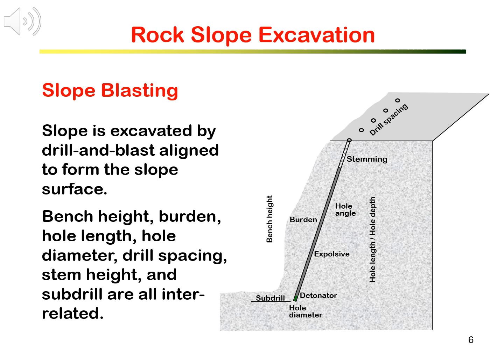A series of holes are drilled in such orientation and alignment to become the slope surface. Key geometrical parameters of drill holes and explosive charges are illustrated here. After blasting, the plane formed by the drill holes is to become the slope surface.